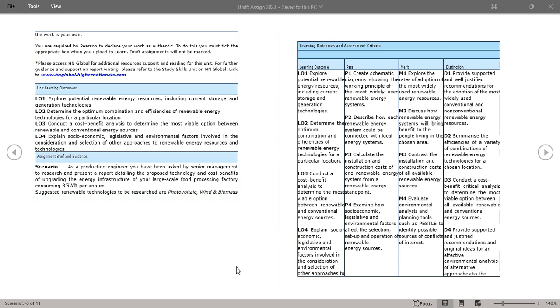Typically, I would recommend doing the cost-benefit analysis through a levelized cost of energy. In terms of my guidance, it would be a 20-year lifespan. Most LCOEs, generally speaking, use 25 or 30 years, which I tend to believe is pushing the limits of really what's achievable. Photovoltaic solar panels, the efficiency does degrade over time. That's a well-known, researched outcome. So that does impact the levelized cost of a PV installation.